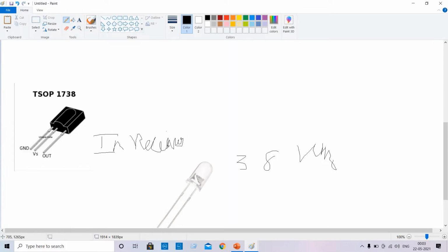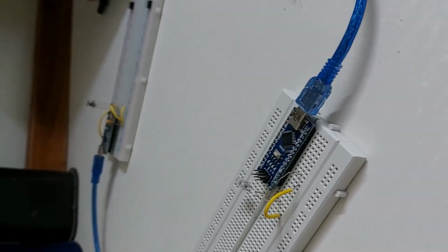The IR receiver consists of a PIN diode to convert the optical signal to electrical, and passes it through AGC, automatic gain control, to eliminate unwanted disturbance from the signal, then through a band pass filter, and lastly through a demodulator to remove the carrier frequency and get the original signal. After that we have the Arduino UNO, which will be explained by Mr. Gurajis.